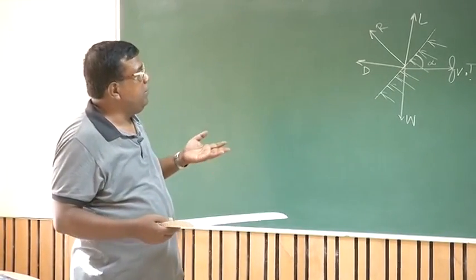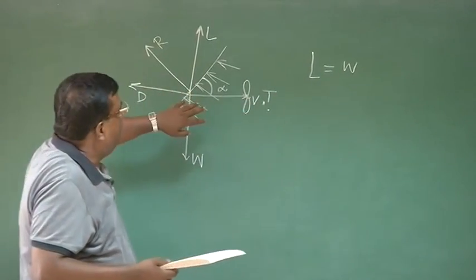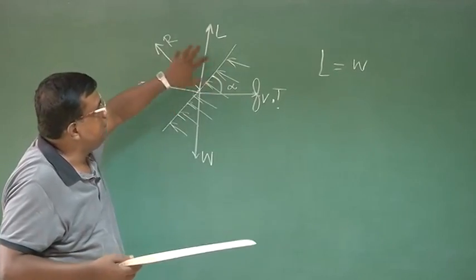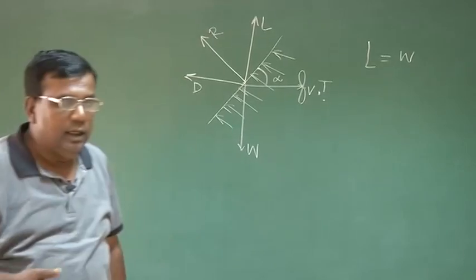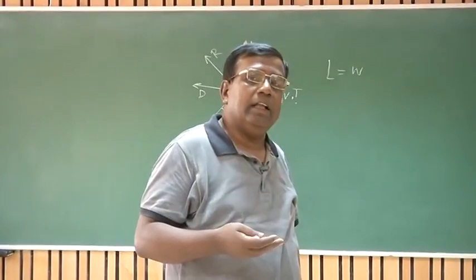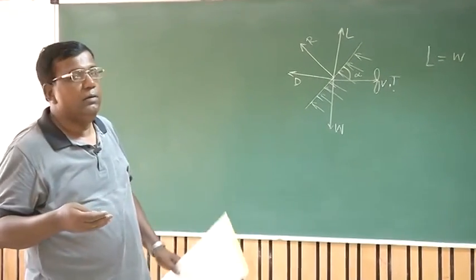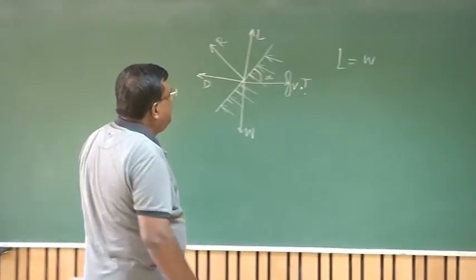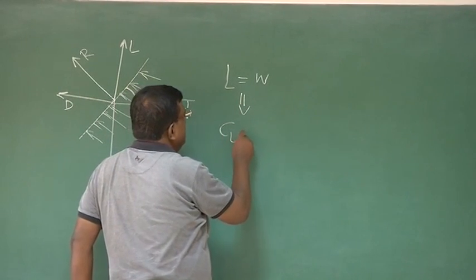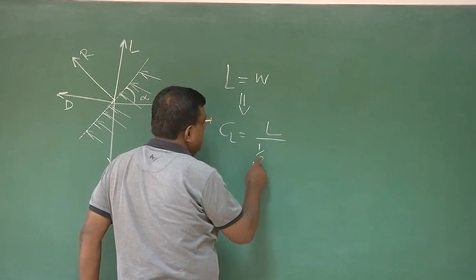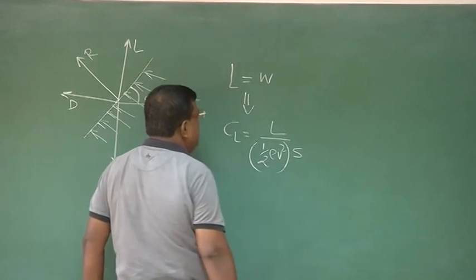And before we go for aspect ratio, we will have a relook here and try to see how I translate this to a pilot in terms of flying the machine. Because I always said, whatever aerodynamics, whatever flight mechanics we do, finally I have to translate this in terms of a language which a pilot can understand. Then from here we realize that we will be operating in terms of CL, which is nothing but lift non-dimensionalized by dynamic pressure into S reference.